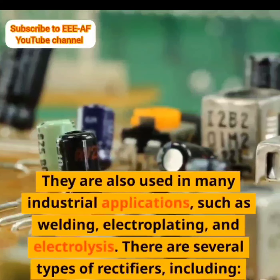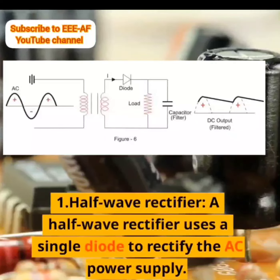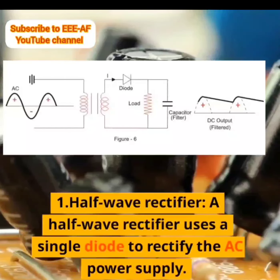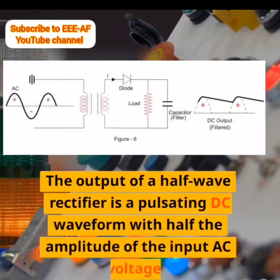There are several types of rectifiers, including: 1. Half-wave rectifier. A half-wave rectifier uses a single diode to rectify the AC power supply. The output of a half-wave rectifier is a pulsating DC waveform with half the amplitude of the input AC voltage.